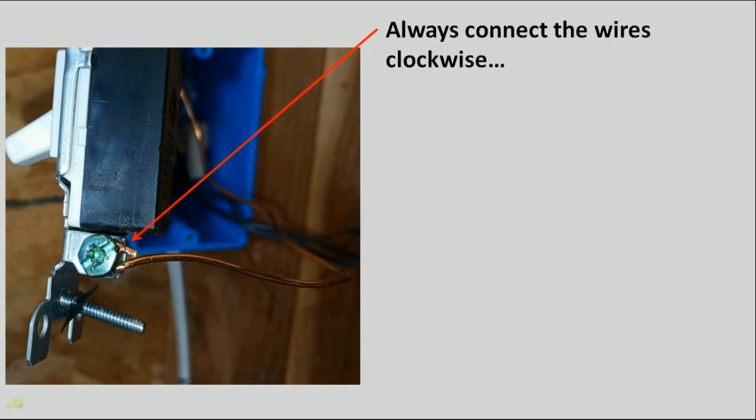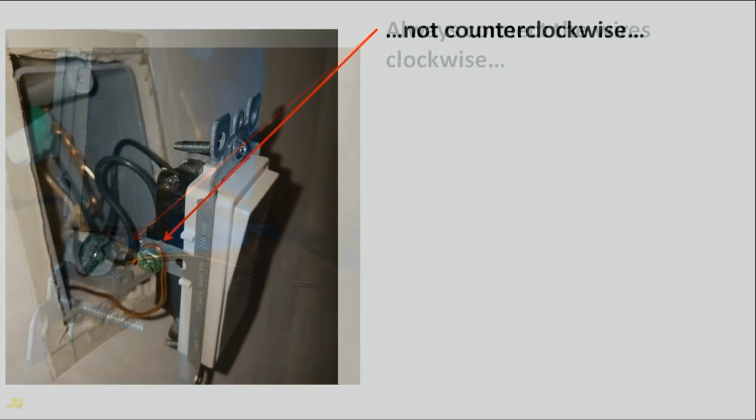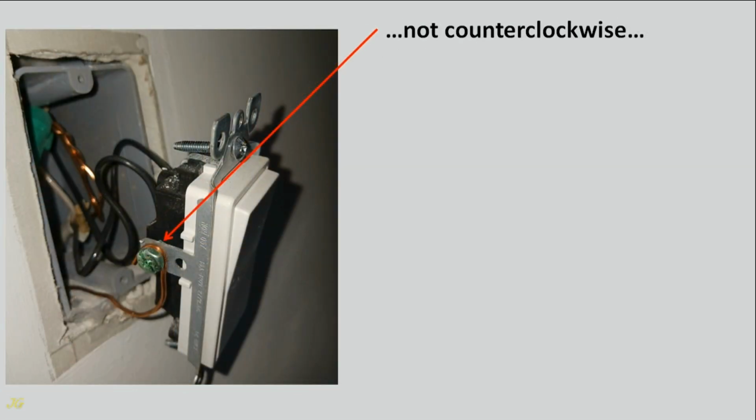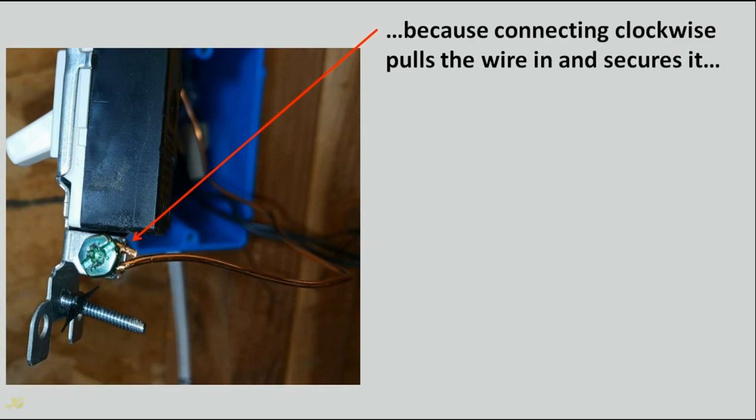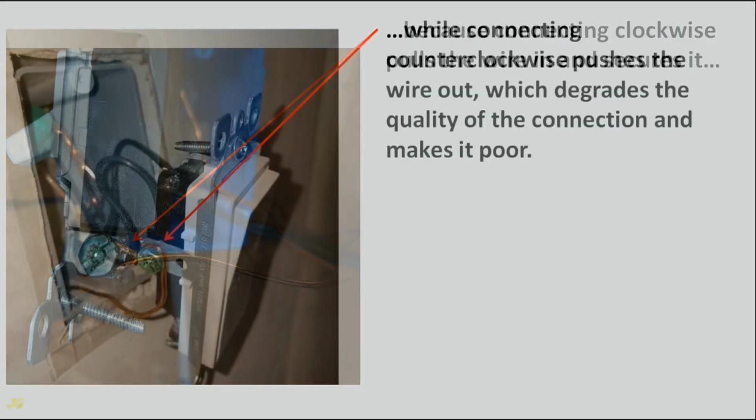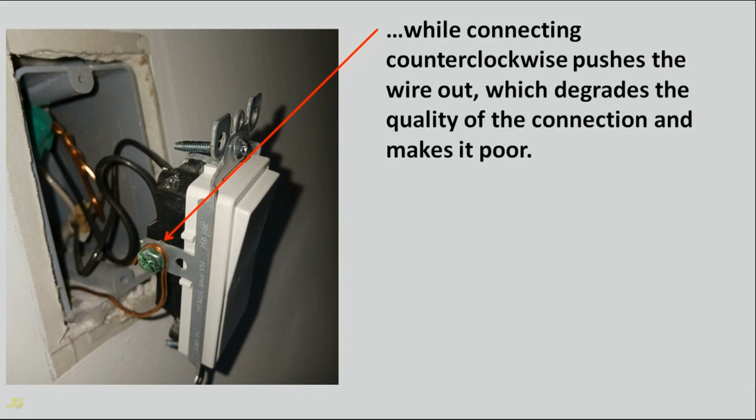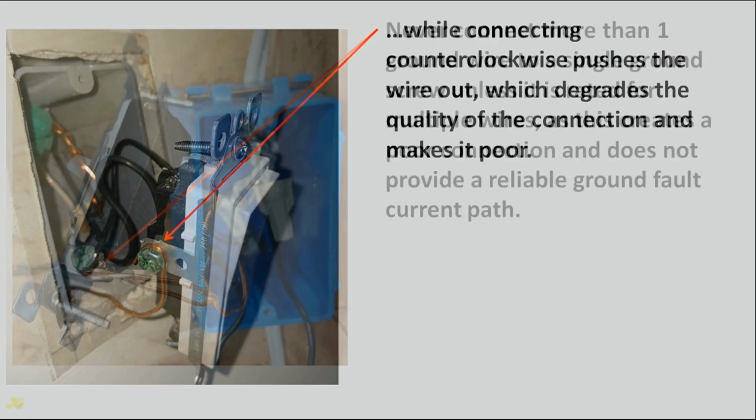Always connect the wires clockwise, not counterclockwise, because connecting clockwise pulls the wire in and secures it, while connecting counterclockwise pushes the wire out, which degrades the quality of the connection and makes it poor.